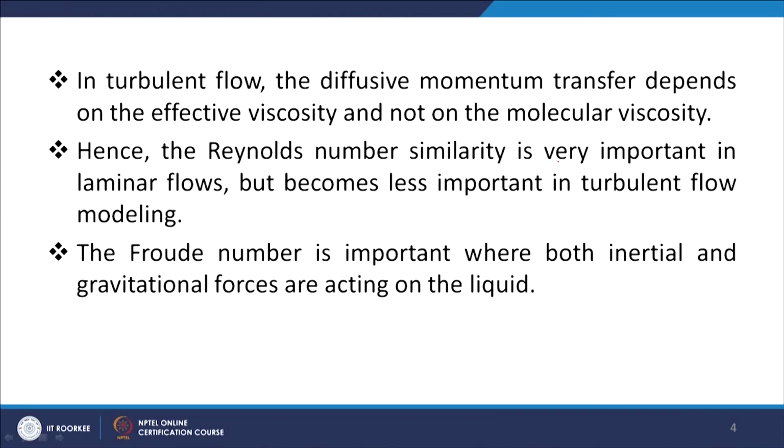So, the Reynolds number similarity is very important in the laminar flows, but becomes less important in the turbulent flow modeling, because in that case the molecular viscosity is not the sole criterion for the determination of parameters, like for the calculation of the momentum transfer.